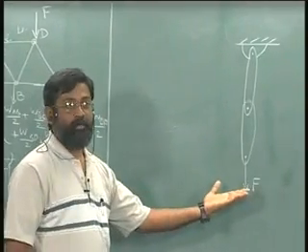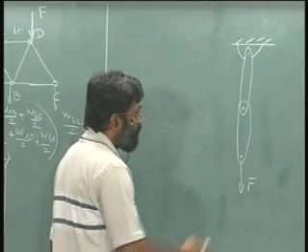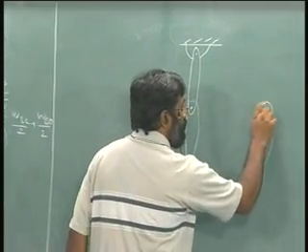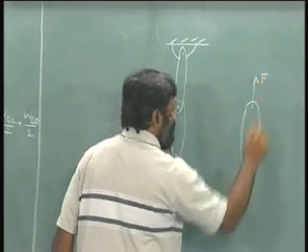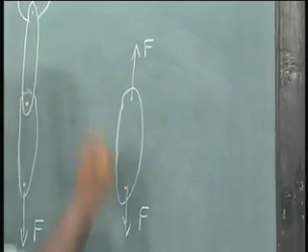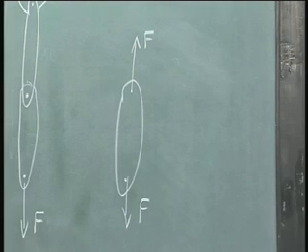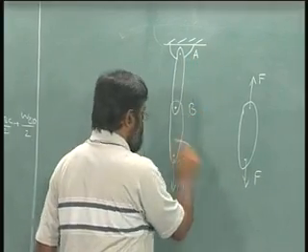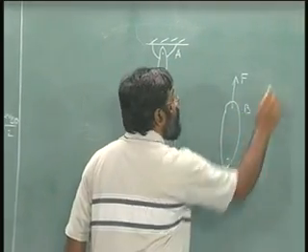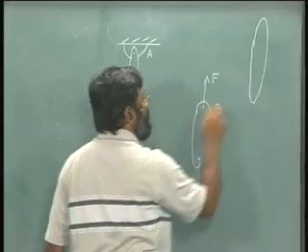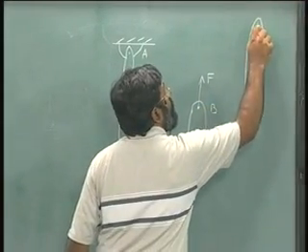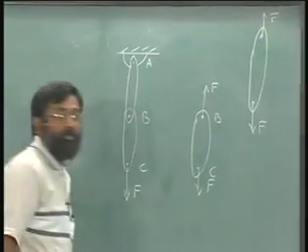Now this is a very simple problem. All I need to do is, I know this is an axial member and therefore there is a force acting here, force acting here. They have to be equal and opposite because this is like an axial force member or a link member. Similarly the other one, let me call this ABC, this is BC, and for AB at this node there is an equal and opposite reaction, which means this will be F and this will be F, no problem whatsoever.